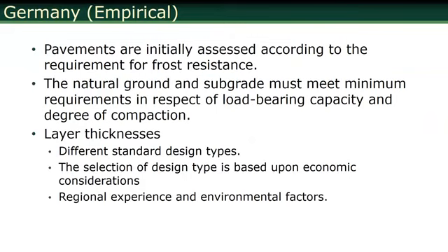Germany, they first look into frost resistance, and then there are certain specifications on load bearing capacity and degree of compaction. The thicknesses are based on a catalog type approach. There are different design types and they choose from a catalog.